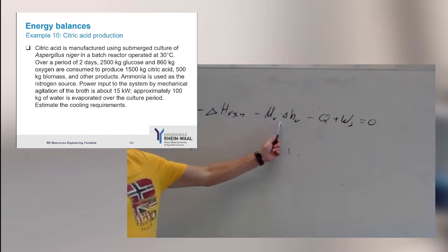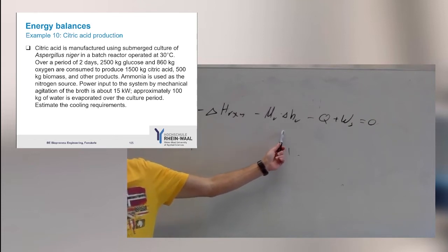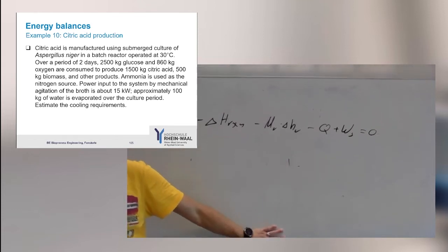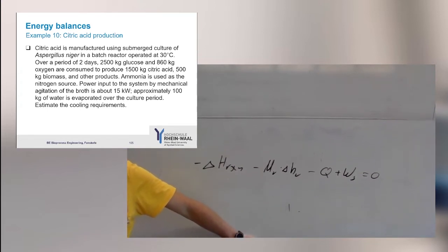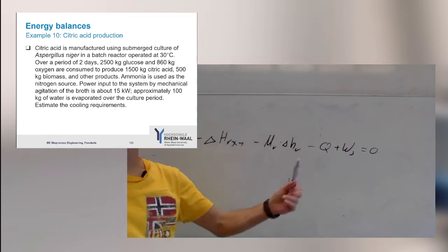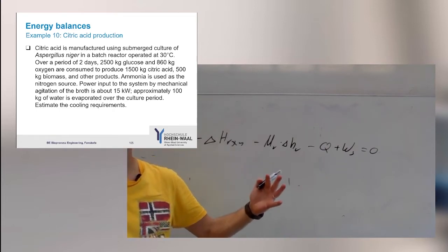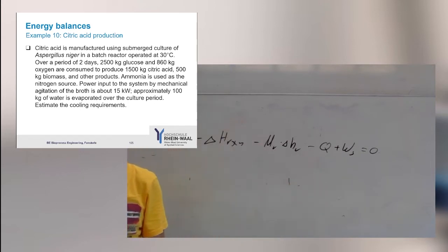And this, for my friends here, is what again, this term? Oh, this is of course not ideal here. Latent heat of vaporization. So the latent heat, the heat of vaporization, exactly. This is the heat required for cooling. So if it's positive, we need it for cooling, and this is what we expect. And this is the heat transported in with our stirrer. So what we need to do now is step by step calculate the heats.